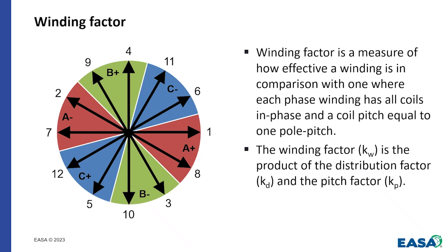If they're buying these neodymium boron iron magnets, with a certain magnetic field strength, how much of that is getting converted into voltage in the back EMF of the machine? Or another way to look at that is how much flux do they get per amp, or how many amps per flux to produce the torque they need for that motor.